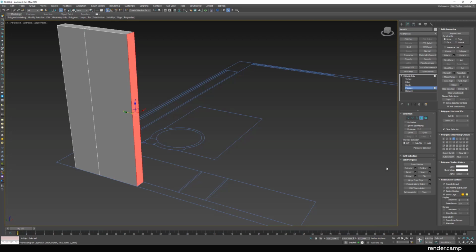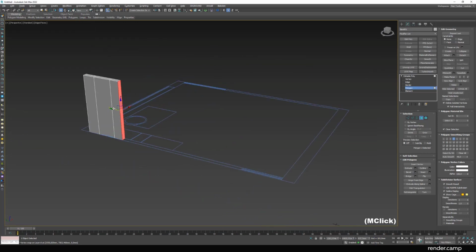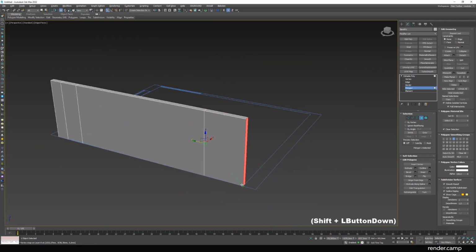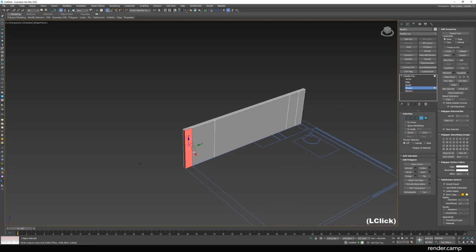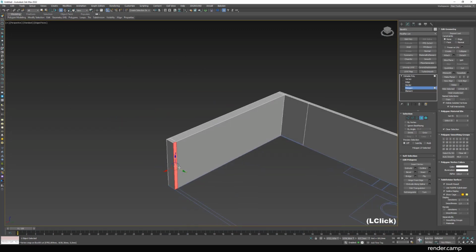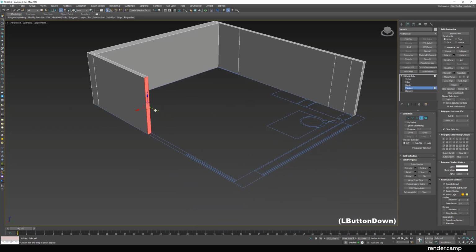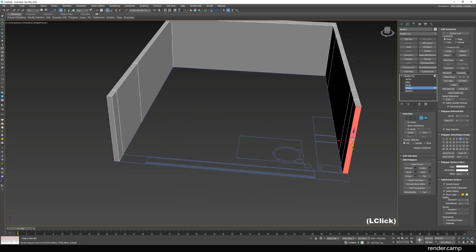If your 3ds Max version is lower than 2022, use Extrude in the settings. Increase amount, then drag to the point. I will continue to create walls with Shift. Select another polygon, highlight other arrow and continue to build. Again, pick another polygon and highlight the needed arrow. Use Shift to create new polygons. Select another polygon and extrude it.